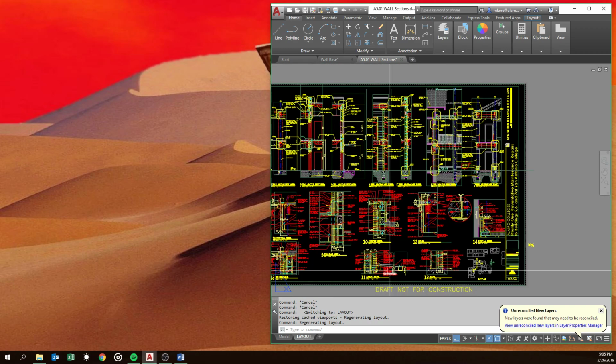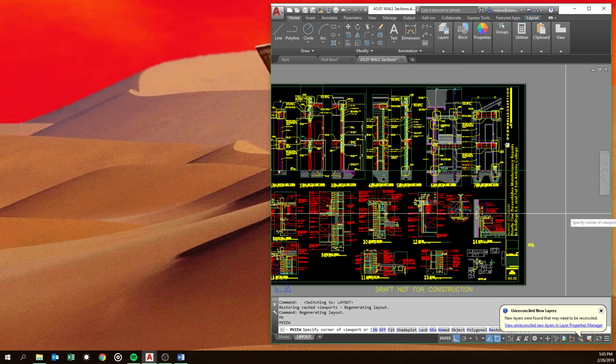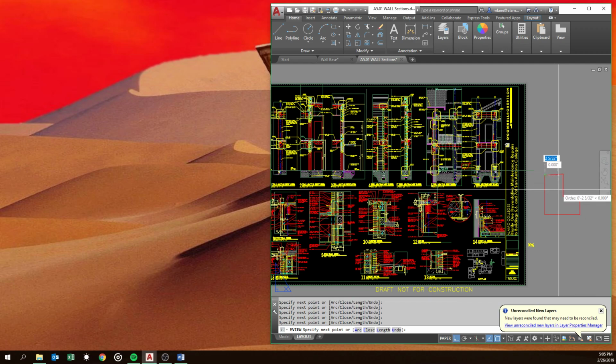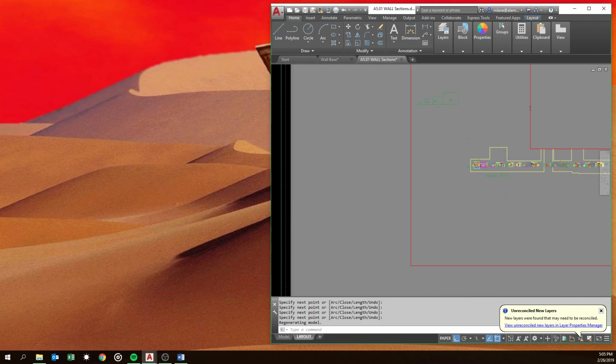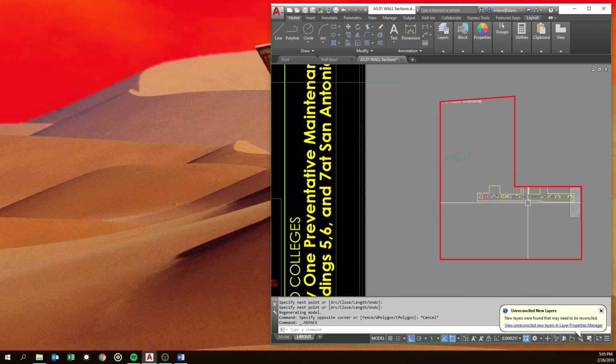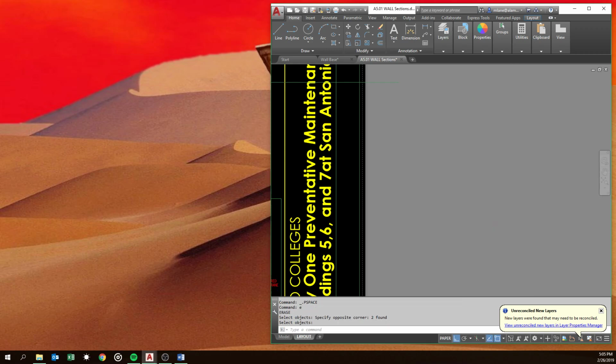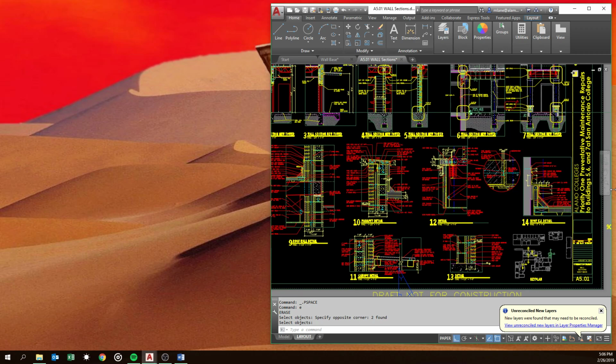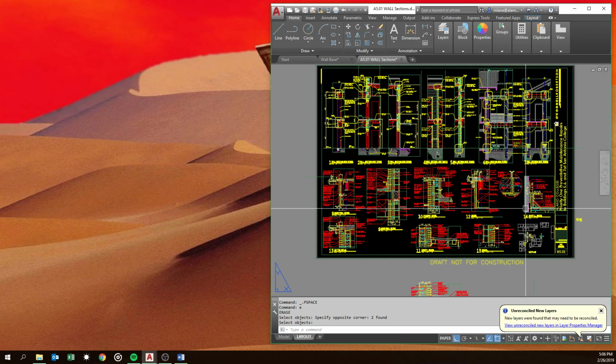Let's look at some of the other things that Mview does. MV, you notice it's got polygonal. Instead of making that polyline, we could actually have hit the P option, and then it lets us draw a polygonal viewport from scratch. Either way, doesn't really matter. If you use the polyline technique or the polygonal technique, you're going to end up with the L shape or whatever weird shape viewport you need. But that's kind of how you'll handle all this kind of stuff.